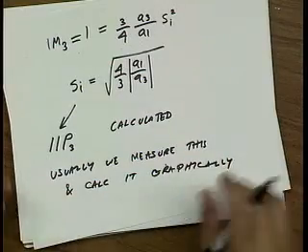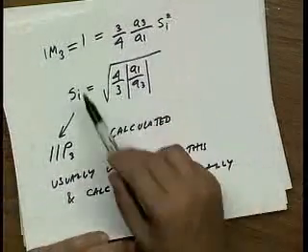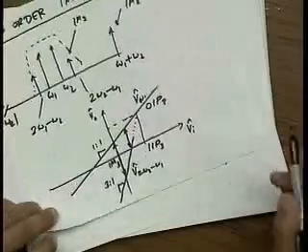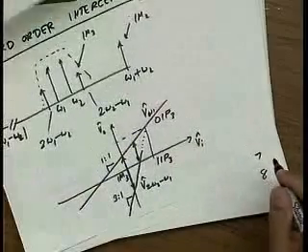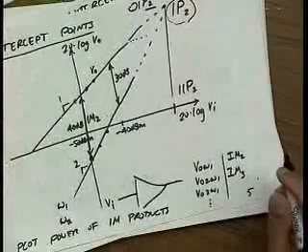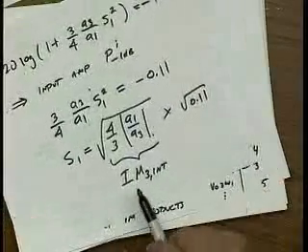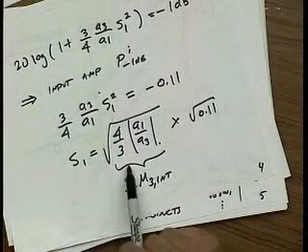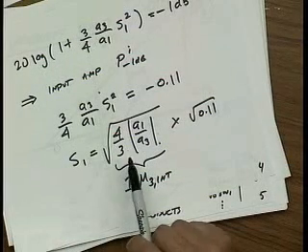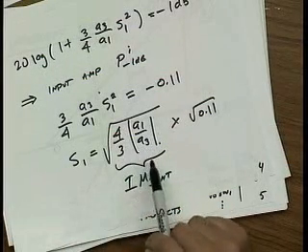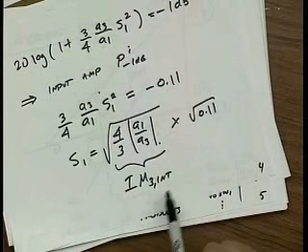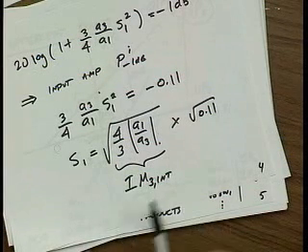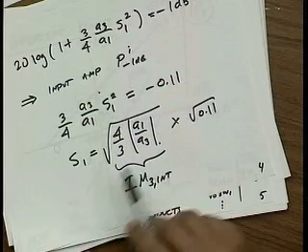that we discussed before. But what I want to point out to you guys is this term in the square root, 4/3 A1 over A3. Let me go back a few slides. Look at the input that I need. What is this input power? This is the input power that corresponds to the gain dropping by 1 dB. It's also the square root of 4/3 A1 over A3. And that's why here I wrote down this is the IM3 intercept point. Okay? So at that point I hadn't introduced it. Didn't want to confuse you guys, so let's go back and look at that.